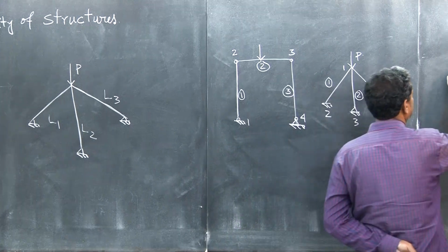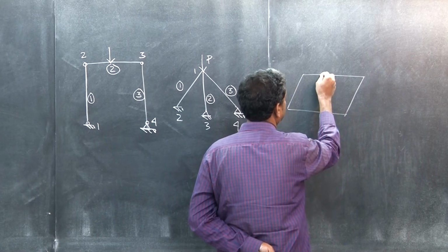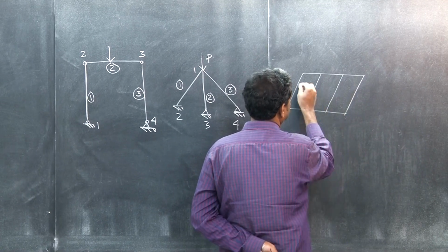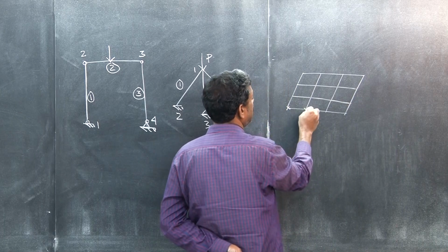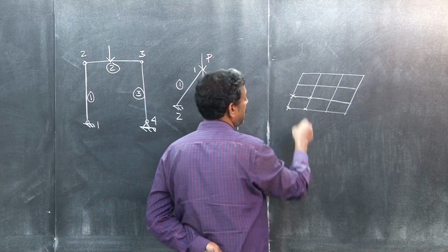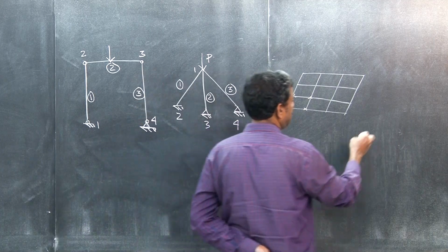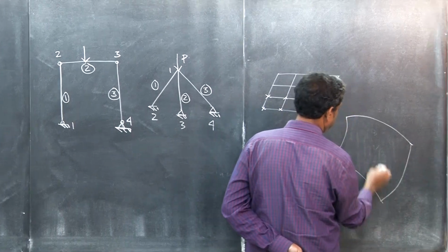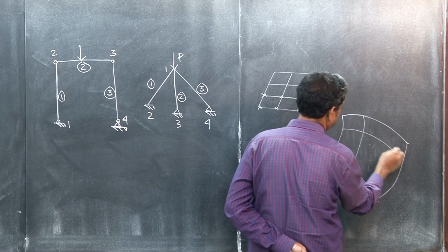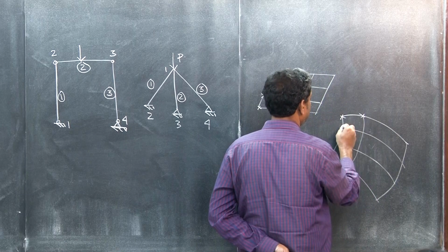Similarly, when we do the buckling of plates, you will see that we can discretize it using finite elements. Here you can use a 4 noded element, or a higher order element, 8 noded, 9 noded element, things like that. Similarly, for shells also you can have shell elements, of course, this will have curvilinear coordinates, right, and then you can have these nodes.